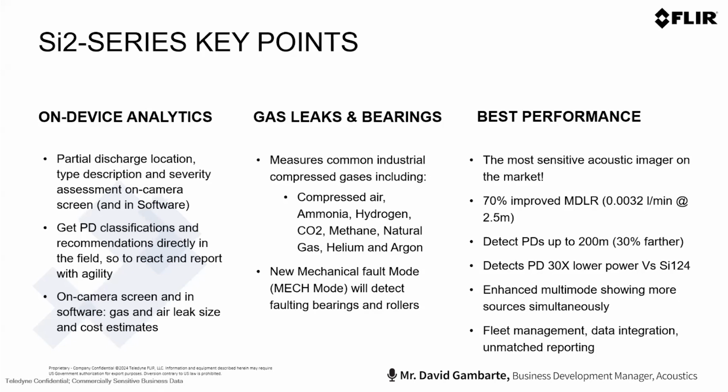Besides everything mentioned in the cloud, it has on-device analytics for partial discharge location, type description, and severity assessment on the camera. The classification and recommendations are also directly on the camera, so you will get them in the field. You're going to be able to react and report quickly when it's needed.